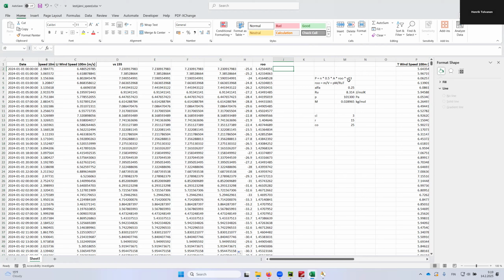So now we have the wind speed that the wind turbine would see. So let's go ahead and calculate the power. Power is going to be, oh yeah, we're still missing the efficiency. Let's put 0.45. According to Betz's law, the maximum is something like 0.6. So from here, this one times 0.5. Oh yeah, and again, we still need the diameter, which is 170 meters.